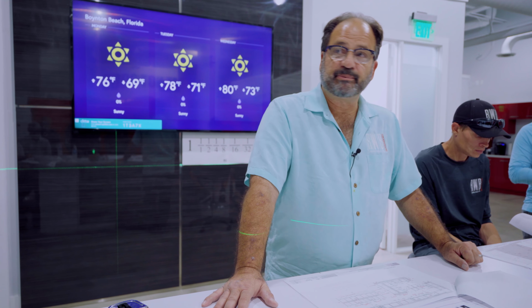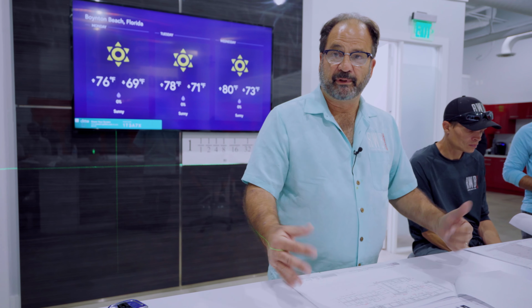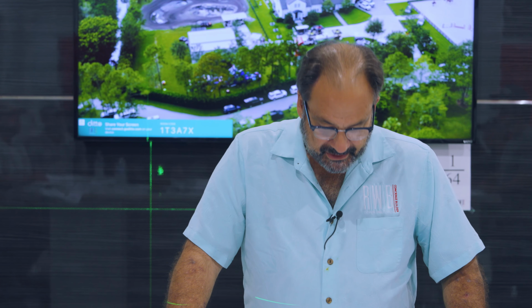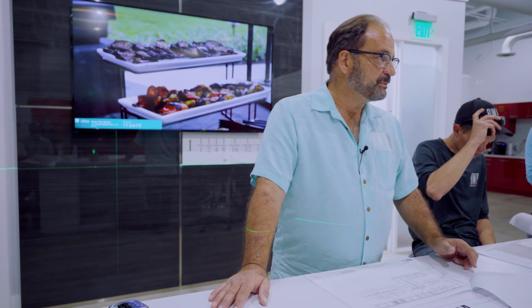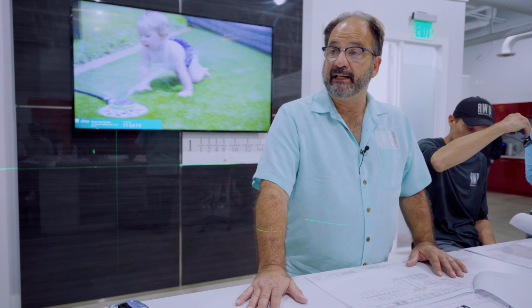I like to put a story pole. I always call it a story pole on the wall. And basically, you're laying out the cabinets on the wall. You're marking it going across. And you're physically laying it out either on the wall or the floor. And in doing that, you're laying out your cabinets and everybody else is looking at the same marks. Remember that you're not working individually here. You're working as part of a team. So whatever the layout you do, everybody else is going to be using the same layout.